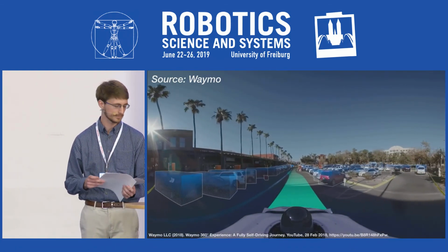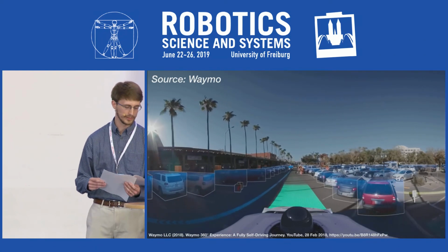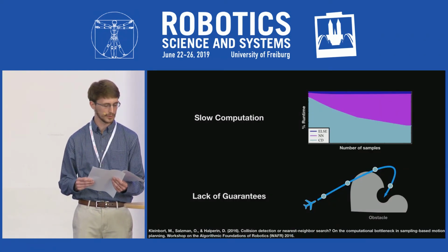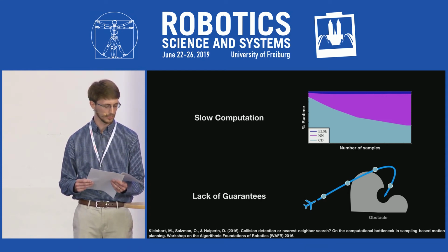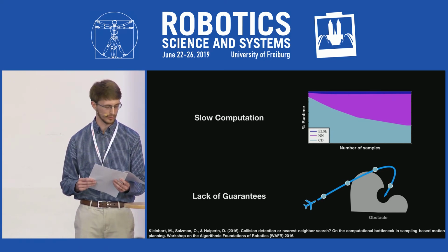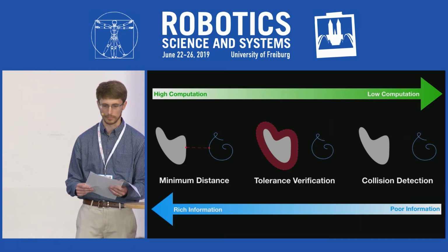serves as a significant computational bottleneck for motion planning algorithms. For example, in sampling-based planning methods, nearly 50% of the runtime is expended in performing collision checks as shown in the top figure. In order to lower computational loads in real-time implementations, collision checks are performed only at discrete intervals along the planned trajectory, which may incorrectly validate infeasible trajectories as shown in the bottom picture.